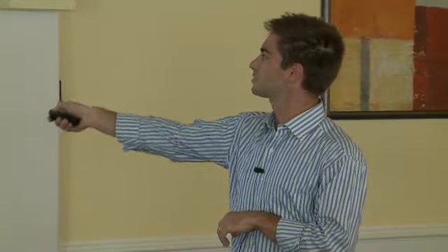And then we have these terms, which we have a little more idea how to control from simple Euler-Bernoulli theory. So we can write these out in terms of the geometric dimensions of the cantilever and some material parameters like the Young's modulus and the density, and you quickly see that this term is proportional to this expression: the width times the thickness squared divided by the length.